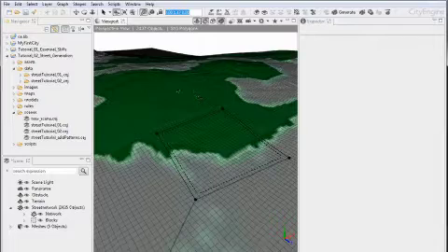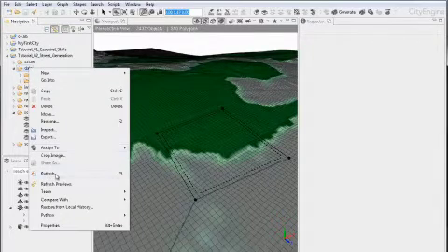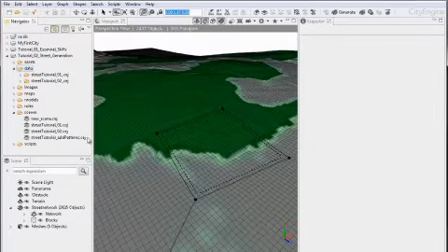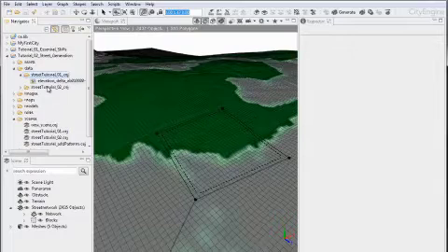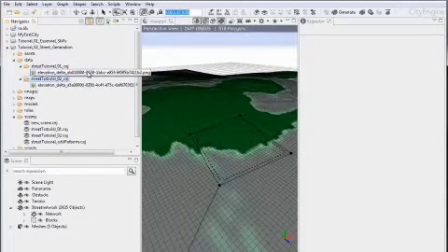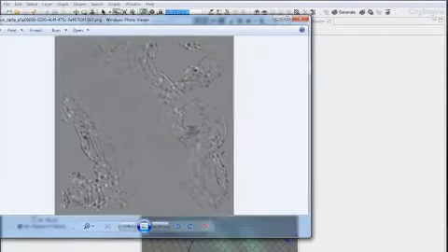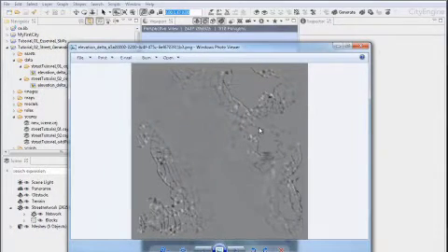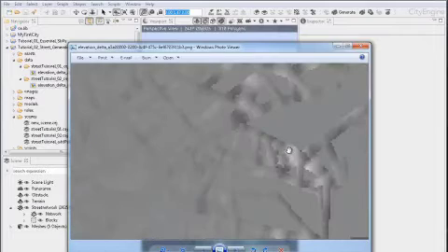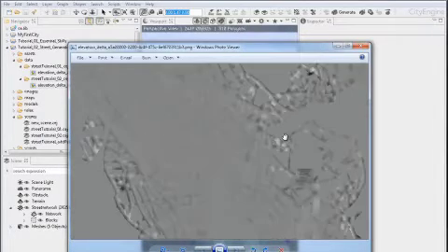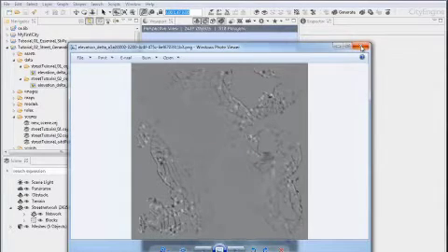So let's go ahead and save the scene, and then go in here and refresh this folder. I have already aligned the data in two of the scenes here, so there are two different delta maps available. As you see, the data is stored in a subfolder of the data folder, which carries the exact same name as your scene file, which in the current case is Street Tutorial 02, which I have open. Now if I open this file, it looks about like this, and you see that the alignment was done by moving some points up and some points down, and this is stored in this 16-bit PNG file.